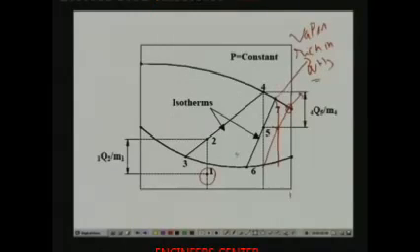That means the whole system is working like a rectification column. So, I have used a combination of two heat exchangers and two separators, and I have started the process with a subcooled liquid. I have heated the liquid, then I separated the saturated liquid and vapors, then I cooled the saturated vapor, again I separated the liquid and vapor fractions, and finally I have a vapor that is rich in ammonia. So, this is actually the purpose of any rectification system where you feed the liquid and you get pure components.